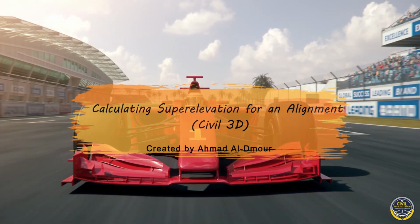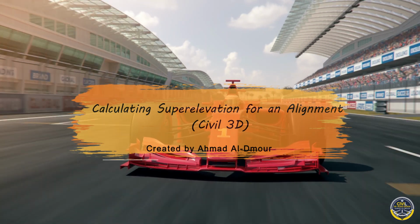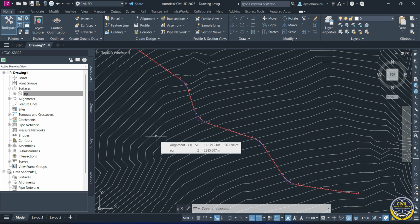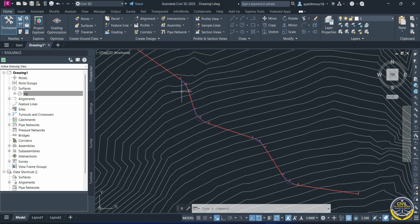Welcome to this lesson. We will calculate superelevation for all curves along a selected alignment in Civil 3D and review the resulting course slopes at critical stations. First, start by opening the Drawing Align Superelevation file located in the Tutorials Drawing folder. Then select the alignment you want to calculate superelevation for, and navigate to the alignment.